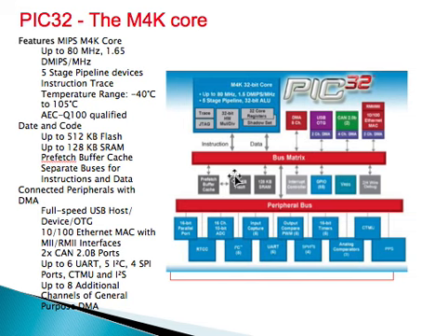This is the internal architecture of a PIC32. It has about half a gig, 512 kilobytes of flash, which is the program space you can use. It has 128K of static RAM, and various caches to speed everything up.